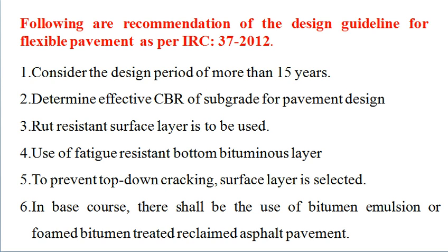That means when bitumen was introduced into the base course and the sub-base course, they became more intact, with better binding between the aggregates, and the rolling action provided strength to these bottom layers. It actually introduced fatigue resistivity into the pavement. Next,